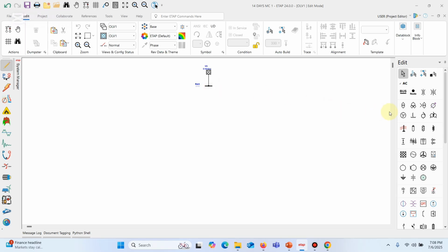Let's say we need a transformer. We go through the same process. We click on it and this comes up. We drop the transformer here. We can see the connection pin is already showing. You can see this is for the primary side of the transformer. This is for the secondary side of the transformer. So to connect this transformer to the bus bar, all we need to do is get the connection pin. We click on it and we have our connection. Take it to the bus bar. The bus bar turns pink. We click on this and we've successfully connected the primary of the transformer.